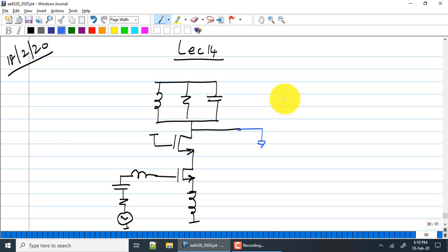Okay, we can also do the voltage, but basically what I'm going to assume is that the cascode does not produce any noise, which we already assume. I want to find out this current. If there is a short circuit noise here, this would be ISCN, right? So basically I'm going to assume RDS is very large, much larger than other impedances. Whatever current flows up into the cascode flows up. If you're doing open circuit voltage, it gets multiplied by RD to produce the voltage. If you're finding out the short circuit current, it produces a short circuit current equivalent to this current flowing out, right?